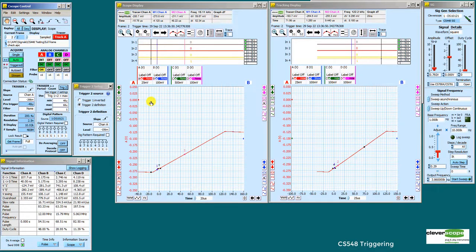So now we're triggering on a slope that's too shallow. This could be that power electronics switch that's turning on too slowly. There it's off, there it's on. So being able to use analog values on the same edge to trigger allows us to trigger on slopes.